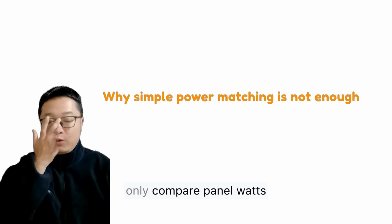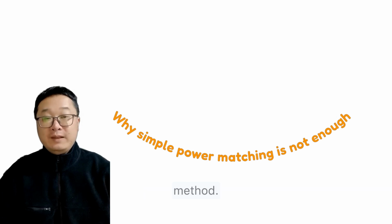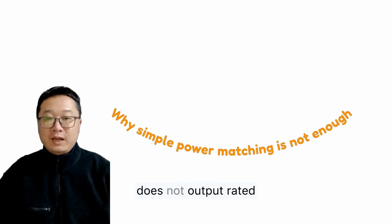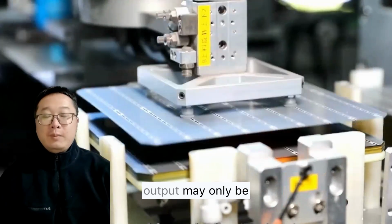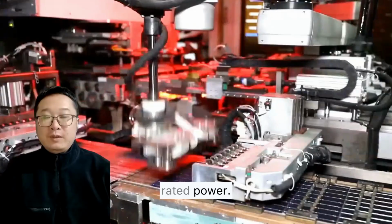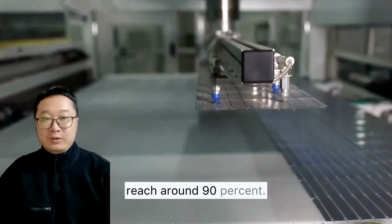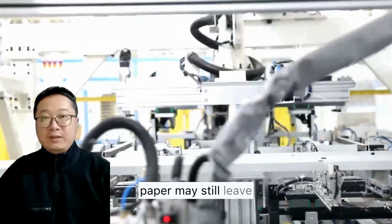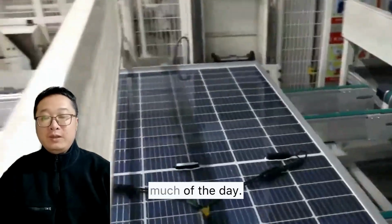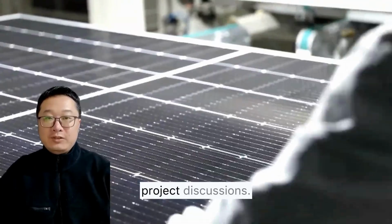A lot of people only compare panel watts and inverter kilowatts. That's fine as a starting point, but it should never be the final design method, because a solar module does not output rated power all day. In normal conditions, actual output may only be around 70% of rated power. Even in very good weather, it may only reach around 90%. So a system that looks perfectly matched on paper may still leave inverter capacity unused for much of the day. This is one of the most common mistakes I see in early project discussions.